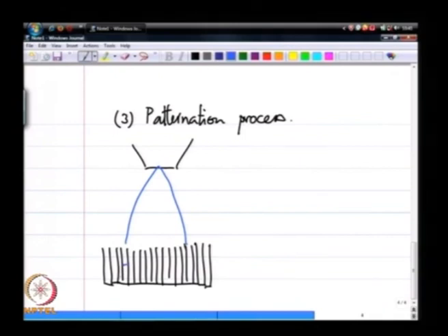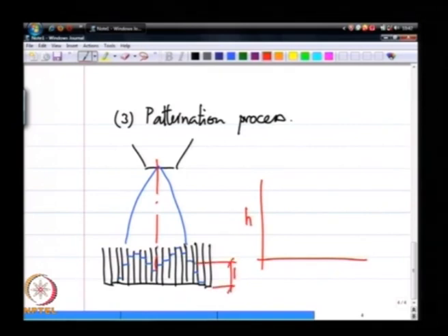From knowing this peak value of the volume flux, and saying, say if this is V peak, I am going to go to a point where the volume flux is 1/10 of the V peak and call that my spray edge. So, the point where the volume flux is 1/10 of V p is denoted as the spray edge.